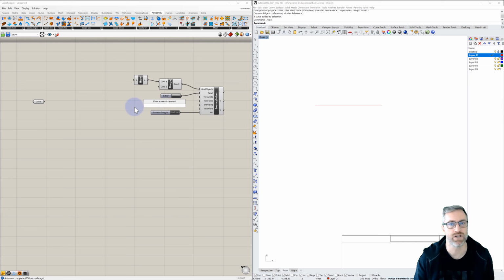And that is, if you want to create a panel, you can do //. This convention comes from commenting code in that it wouldn't be normally read. And so it does make sense that we could comment something by adding a panel. And it's nice, it's on the top of the keyboard, or at least for me, the number pad on my keyboard. So // and then 50 enter gives us a nice little panel that has 50.